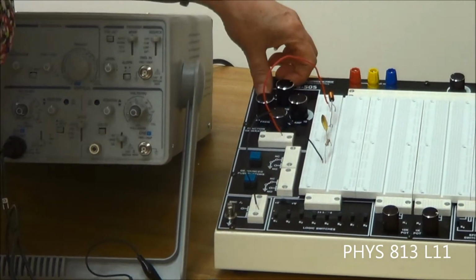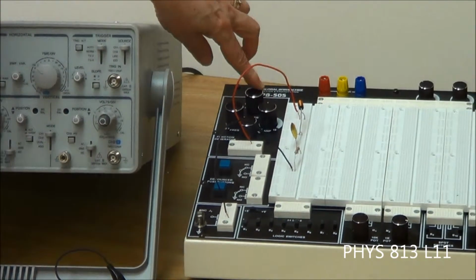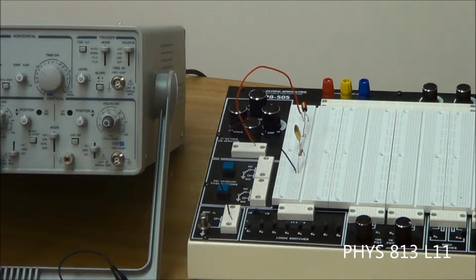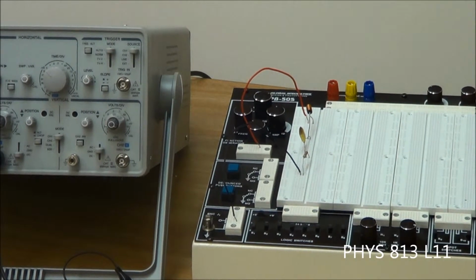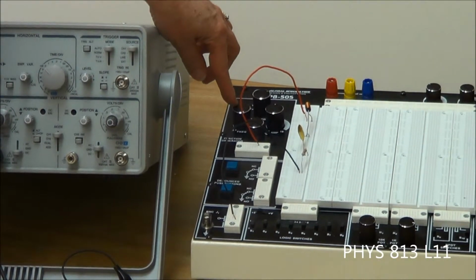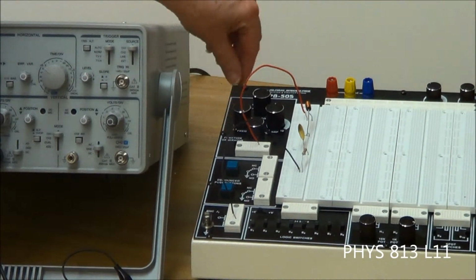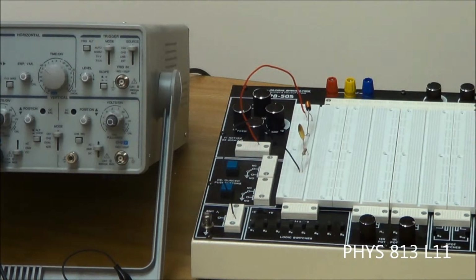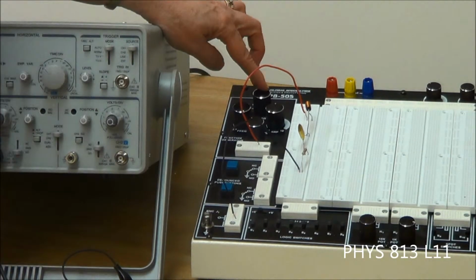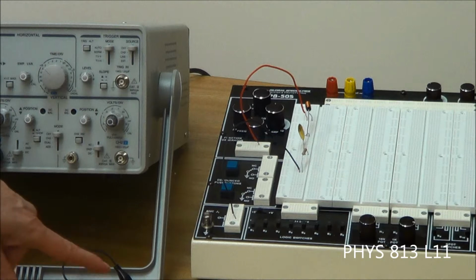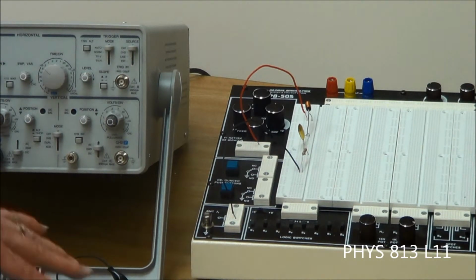But you want 10K, and the reason you want 10K is because since I already know where the resonant frequency is, we're going to put it there. And then we're going to put our variable or continuous dial for frequency clear around to the right at 1. We're going to decrease that. So we're essentially starting at 10K, 10 kilohertz, and we're going to vary the frequency down and watch what happens to the voltage across the resistor as soon as I get this connected.